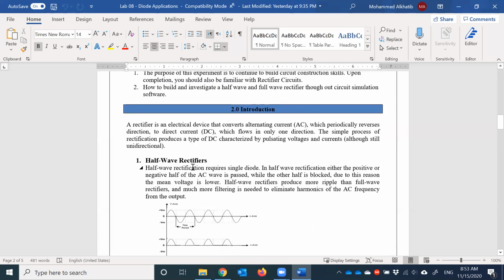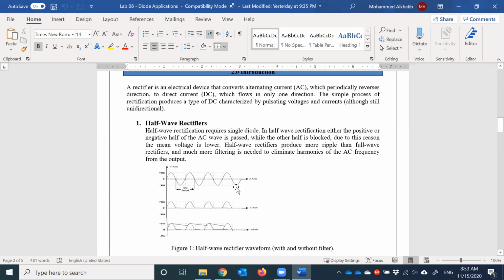So for a half-wave rectifier, we have it like this. That's my input signal. That comes from the outlet. Now, when we apply it to a half-wave rectifier, only positive half cycles will pass. If you guys remember, the diode will reject the negative half cycles. What will happen later if you apply a filter, and basically it's a capacitor, my, let's say, pulsating wave here will be converted to this waveform here. And we will see now how the output will look like at each stage.